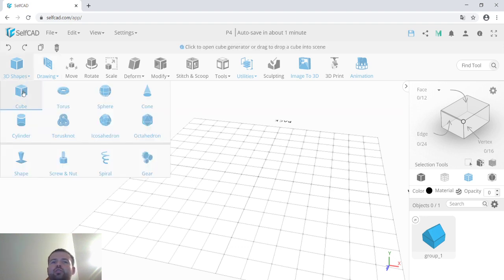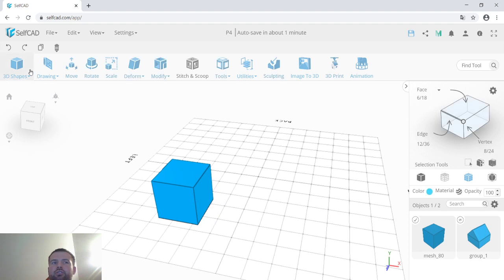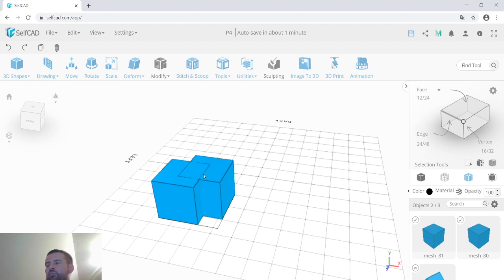And union actually makes a bigger difference because the meshes that come out from union are watertight, which means that if you, for example, merge 2 objects which would result in faces being inside of the mesh, let's say even this example, if you do a union, you actually remove the inner parts and the object is ready for printing after union.